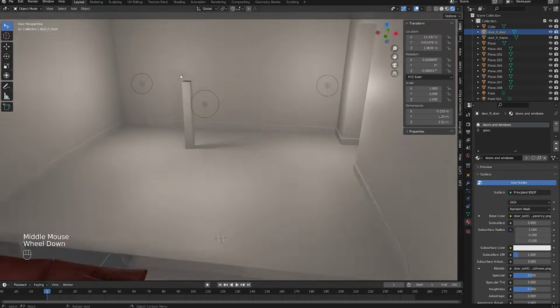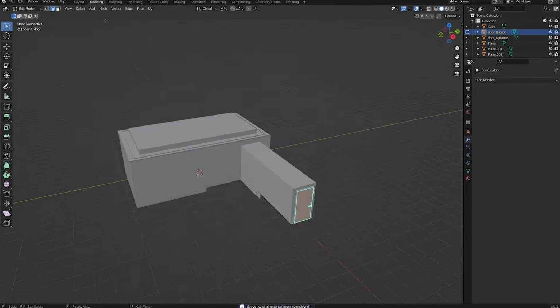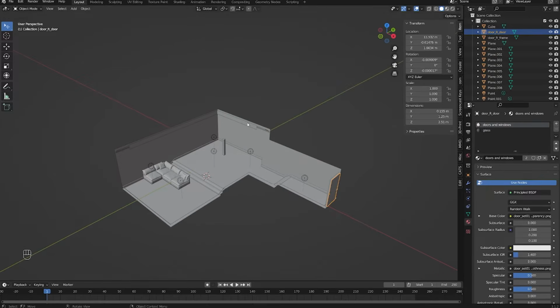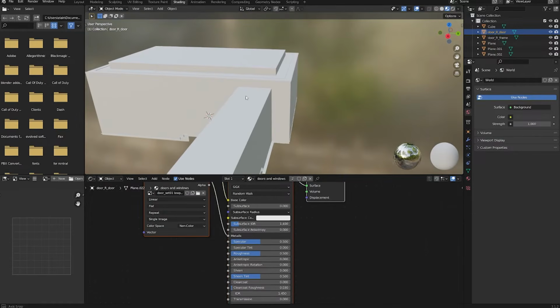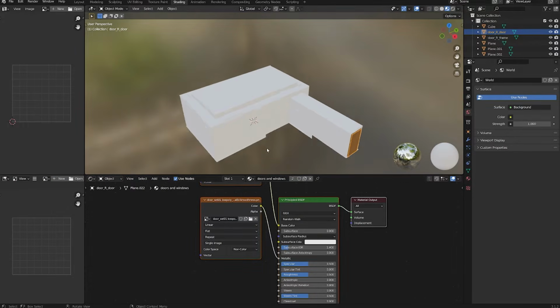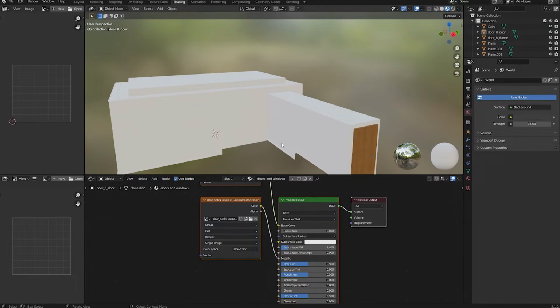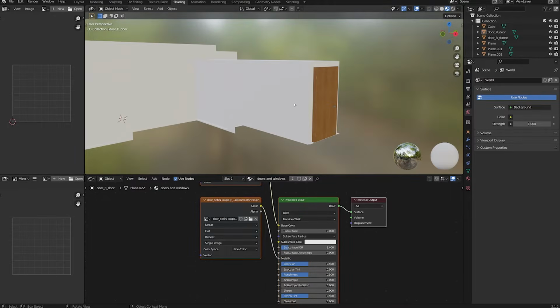So let's go back to Blender. This whole time we've been working in this layout. I think by default you're in the modeling viewport, but this whole time we've just been in one tab, and by default Blender has all these different tabs that you can go into, and we are going to want to go into the shading tab. So click shading, and by default it'll put us in the material preview viewport shading option. Down here in the node editor is where we can begin to add textures to the project. To add a texture to an object, we need to make sure that that object has a material. So let's just look at the store as an example.